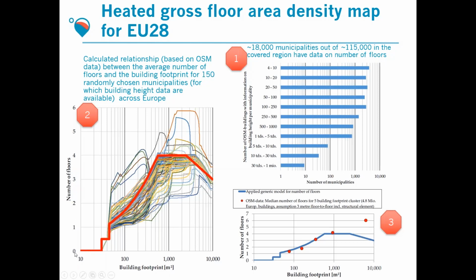And we try to see how is the behavior between building footprint and the number of floors in those 150 municipalities. The idea was to generate a function which can be applied for any regions, of course, roughly, and to find out how many floors different buildings have depending on their footprint, because the data on building footprint are more available compared to the number of floors or floor area.